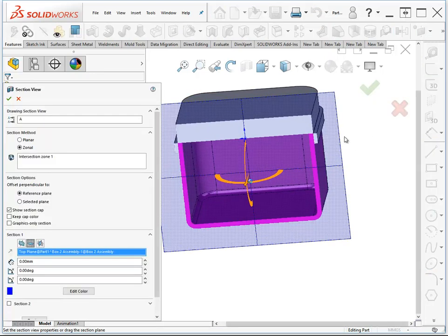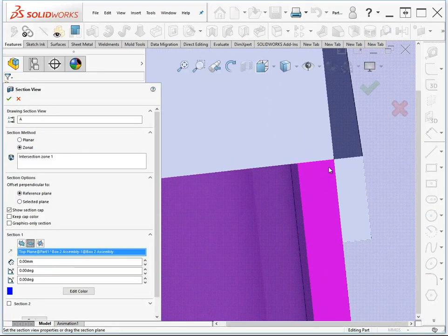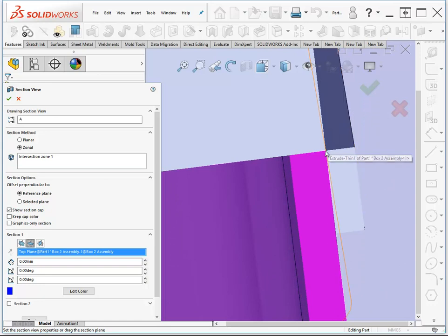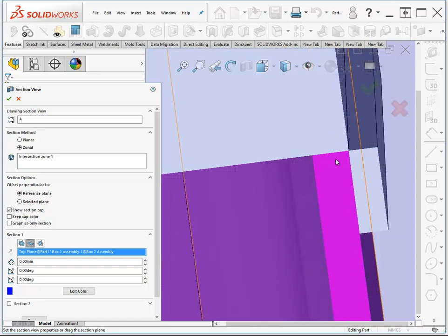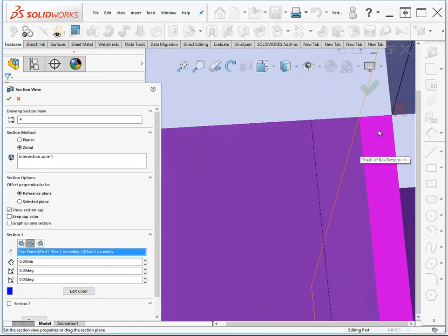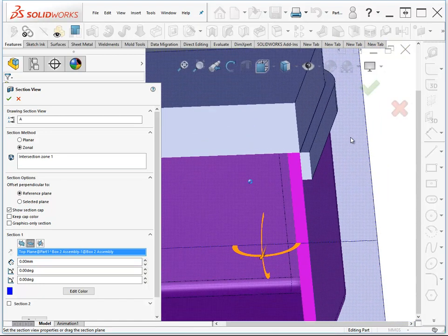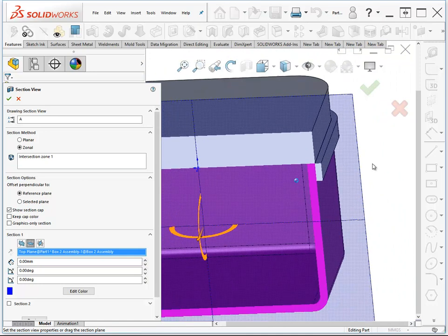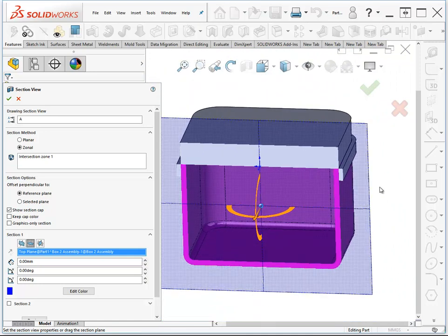They come together here at an edge, and an infinitely thin edge. So that's what we call the zero thickness, and CAD has a real hard time dealing with this sort of geometry situation. So whenever it happens, SolidWorks is going to tell you that you have a couple of options. One of them is that the feature fails, and the other one is that you get multiple bodies.